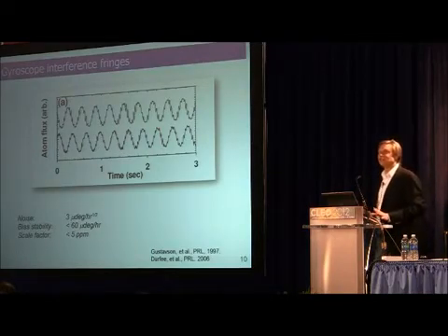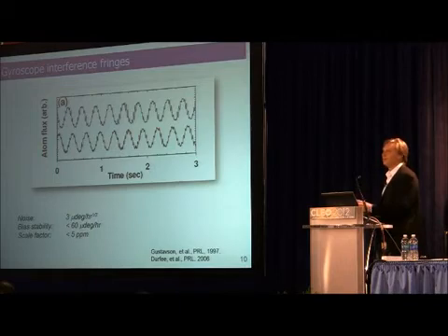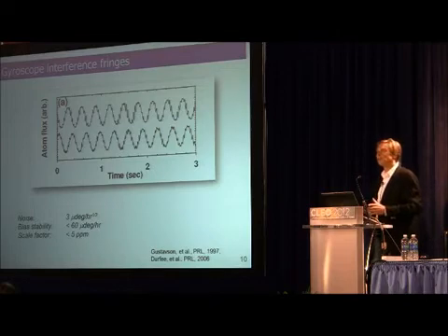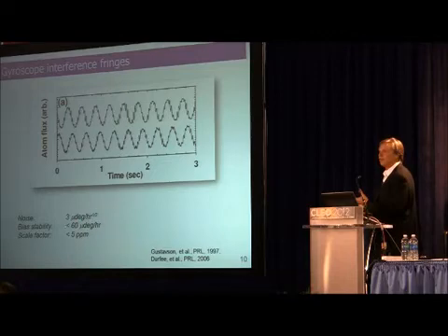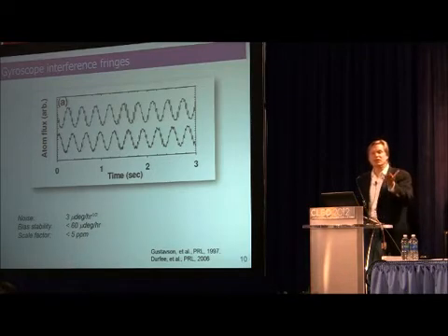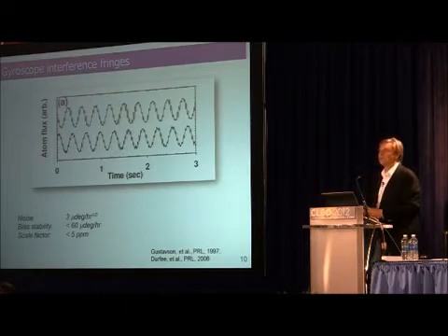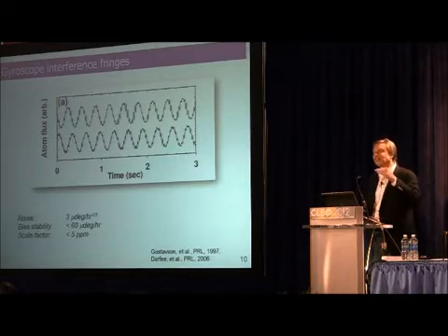Again, for technical details I don't want to go into, but I can just tell you, if you're a navigation engineer and you're looking up your gyro handbook, you say, well, what do I care about? You care about the angle random walk of a gyro. A commercial fiber optic gyro is about a millidegree per root hour angle random walk. This gyro here, that behemoth, was 1,000 times better. You care about the bias stability, how much the sensor drifts around when there's no input. About 100 times better than the state-of-the-art. Scale factor stability, and a lot of these gyro attributes, it just looked like it was better to build them with the atoms.